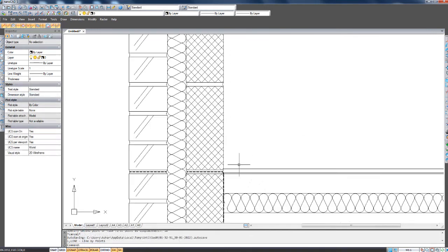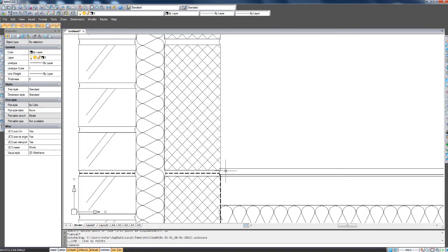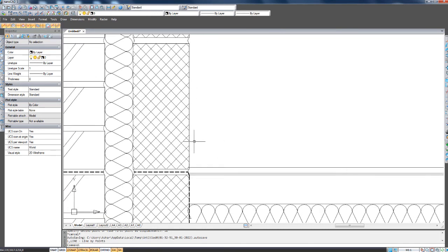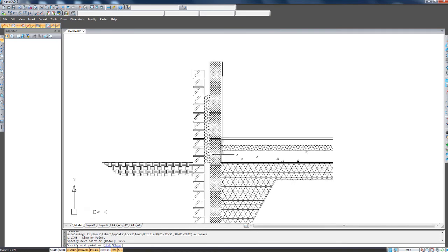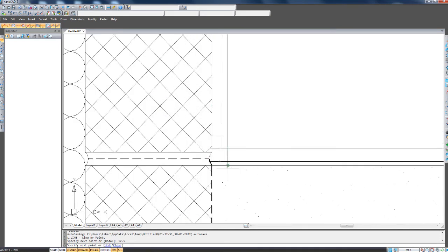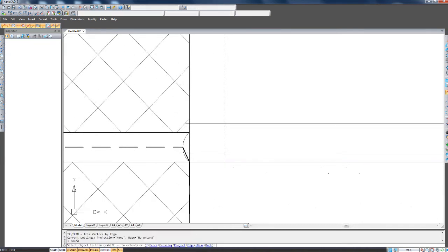Now I want to put a wall board on the wall here going down to the concrete, and a skirting board by 12.5 mil. That's usually the thickness of a wallboard. There's our pointed seams. I'm going to trim these carpets back.